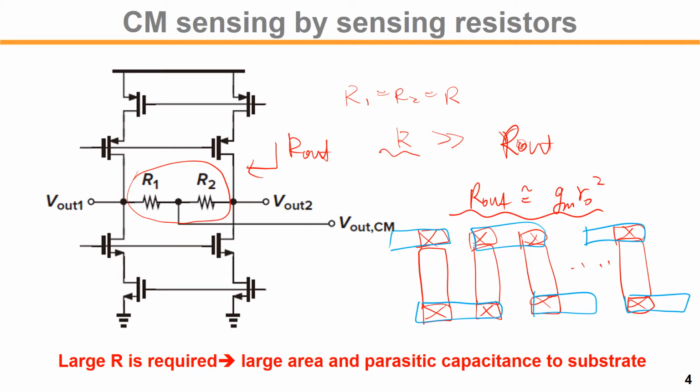The situation is getting better because with sub-micron CMOS, and even now nanometer design, the width of the poly can be very small. R is proportional to the length over the width. If you make the width smaller and smaller compared to L, you can get a large resistor. But what would be the limiting factor for the width?